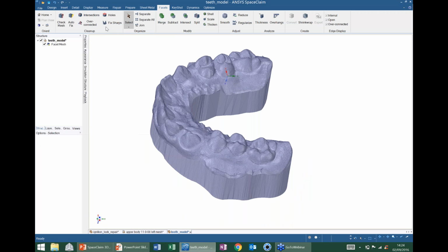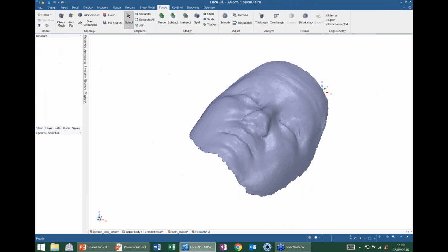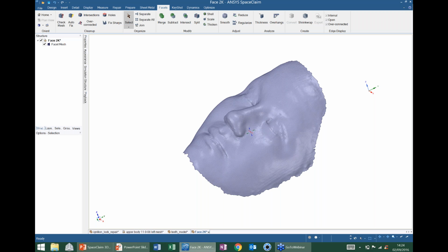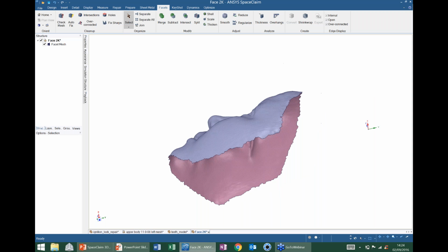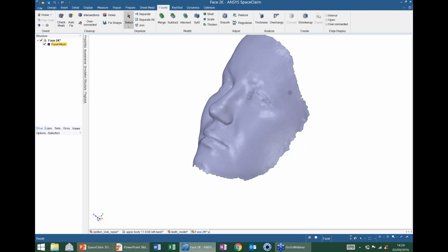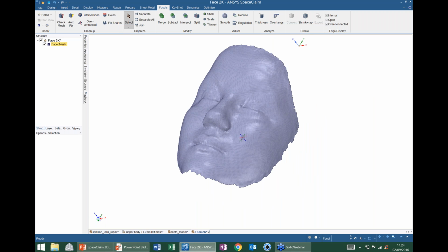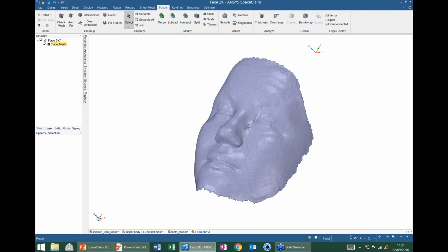Okay, and I'll jump onto my final example now. So what we have here is something similar to our last model. It's some scan data. It's a single surface, but there's another quicker way of getting this ready for 3D print. So if you want to just quickly thicken it up, give this single surface a thickness, and then pop it straight into the printer, that is really easy.